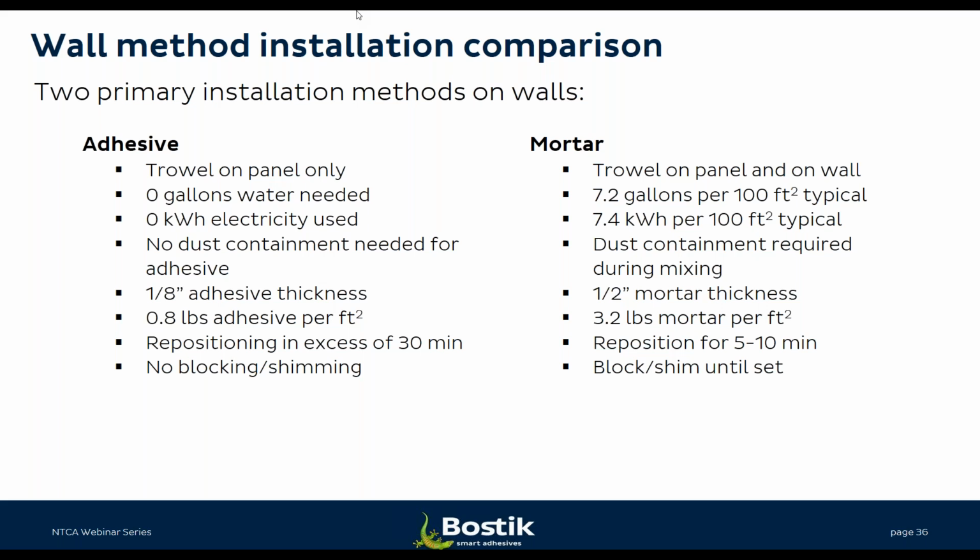There's also a minimum or a thinner thickness that's required in terms of the overall adhesive depth. It's around 1/8 of an inch in comparison to a 1/2 inch for mortar thickness, which again contributes to additional less weight for the installation time and a greater increase of repositioning time. So in this case, it's a little bit more than 30 minutes, whereas many of the mortars are in the realm of 5 to 10 minutes.